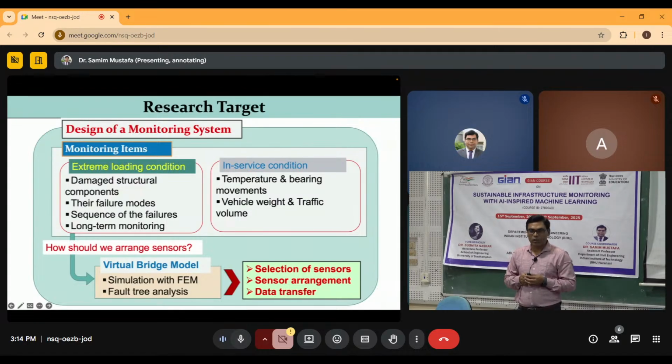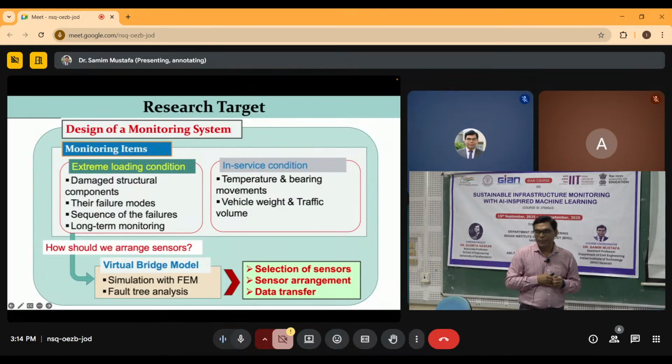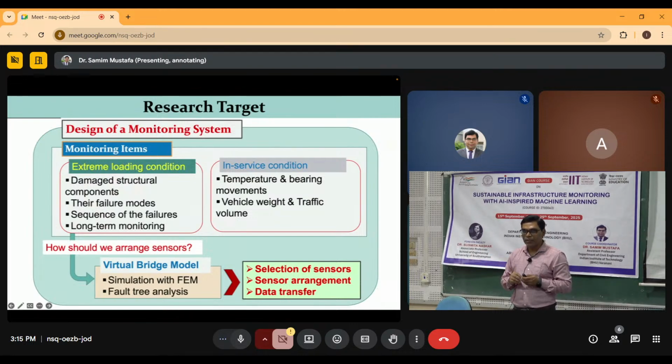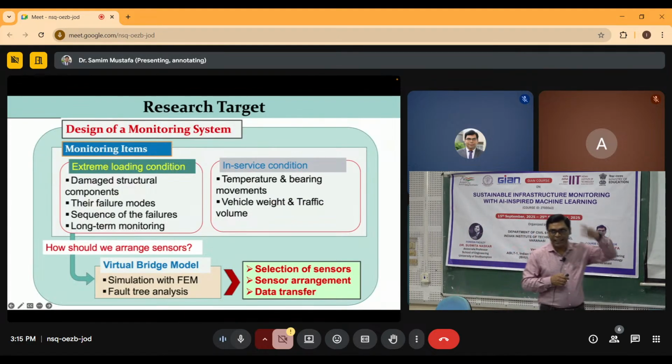So one thing that is possible is that you build the finite element model of that structure in the finite element software, of course a full scale model, and then you run the earthquake analysis, or seismic response analysis as we say, using an actual ground motion, some large, high magnitude or high intensity ground motion. Then you can see how the response is coming.